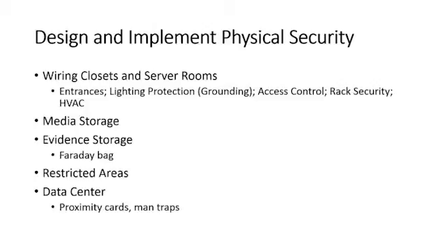We don't want our server rooms and our wiring closets, our comm closets, getting too hot. Heat is not good for servers. Heat is not good for our electrical equipment. On the flip side, being too cold in there is not good for them either. We want it kind of cool, right? 60, 65 degrees. Now that might sound a little chilly for a human, but we're not hanging out in there. This is not the break room. But this is a really good idea for your electrical equipment because you do need to keep it somewhat cool, but we don't need icicles hanging off the servers. Something else, and we'll talk about it a little bit later when we get to utilities, is humidity control. Keep that in mind till we get there.